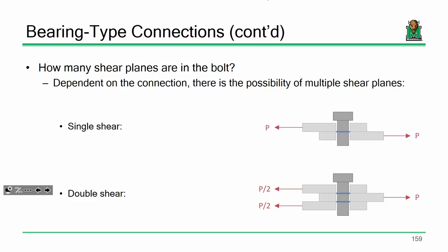Now, what ends up happening is this. This bolt down here is twice as strong as this one right here. Now, I'm not saying that the bolt magically got twice as strong. What I'm saying is that I've got to shear through more bolt to fail this one than that one. I've got two areas that I've got to shear through. So again, it's not like the bolt got stronger. It's just there's more material to get through to snap that bolt, not in half, I guess, snap it in three pieces. Does that make sense? Everybody okay with that?